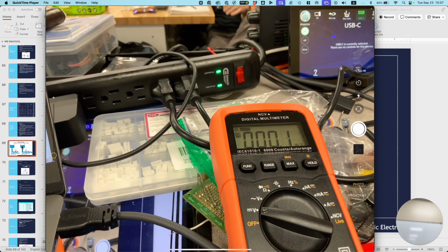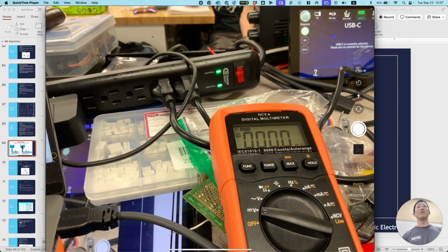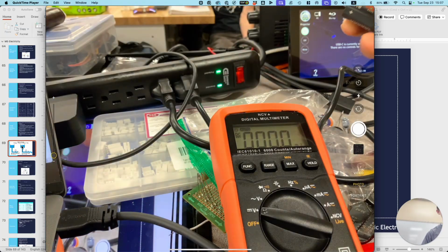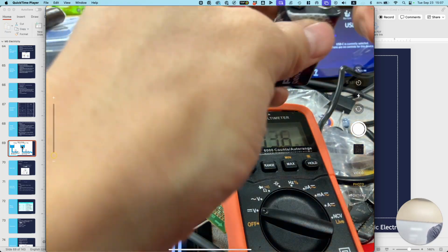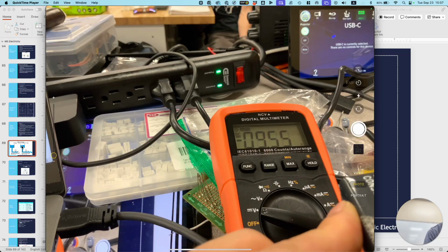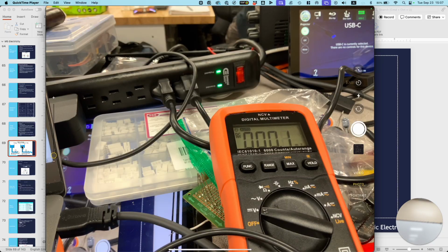Yeah, you have a 9-volt battery here. I've actually taken apart one of these things, and what happens is you just have six 1.5 volt batteries in here, like miniature versions of that. Just think about that. What's 6 times 1.5? 9. Okay, so that's basically what they did. They just put six of these little things in there. So anyways, nominal is going to be 9-ish. We'll see. Okay, there it is, 9.56. So it's pretty fresh still. And I think when it drops to like 8.5 or something like that, then it's usually not usable anymore.